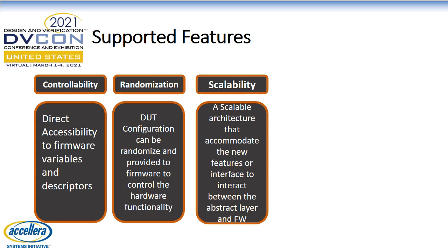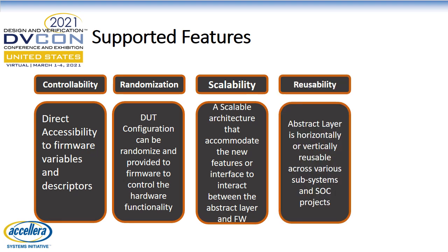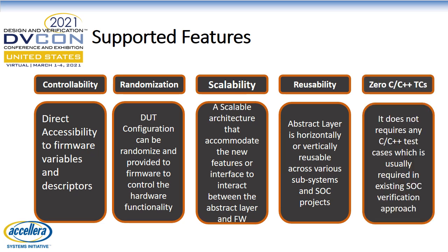Scalability: the abstract layer has a scalable architecture that accommodates new features, like adding additional descriptors between the abstract layer and firmware. Reusability: the abstract layer can be reused across various subsystems and SOC projects with slight modification as per your project needs. Zero C, C++ test cases: as the firmware configuration is controlled inside the abstract layer, it does not need any C, C++ test cases